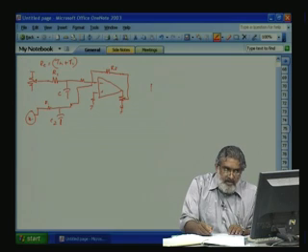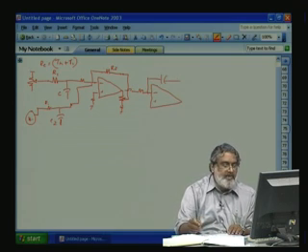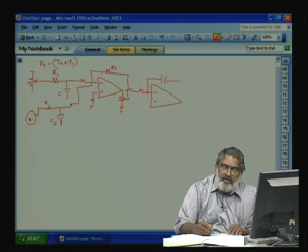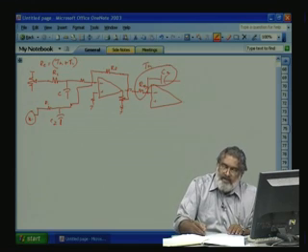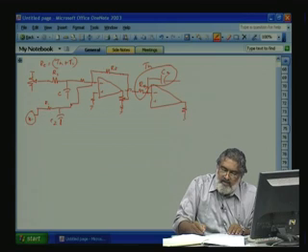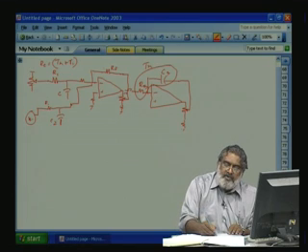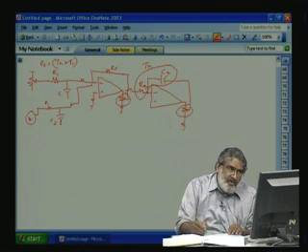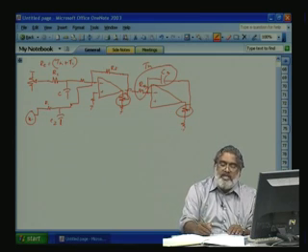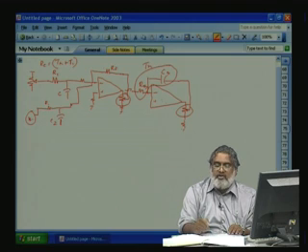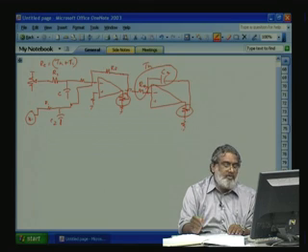Then you have the integrator. We are not disturbing this one; we will make Tn equal to R3 C3. This is our Tn, and fine tuning we can do here. This part is the P controller, and this is for the I control, which we can control independently without disturbing the capacitor and R3. We do not want to disturb R3 because it will affect the input bias current requirement of the operational amplifier, and changing C3 online is very difficult. So, we will use this one.